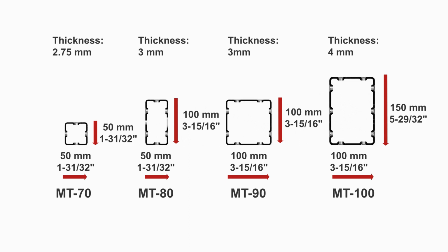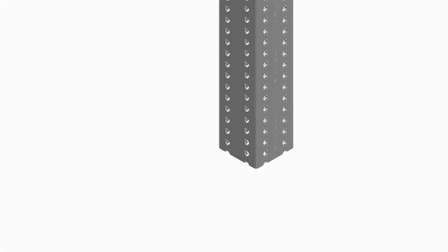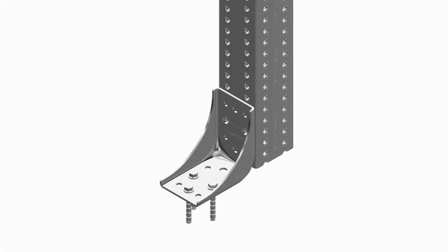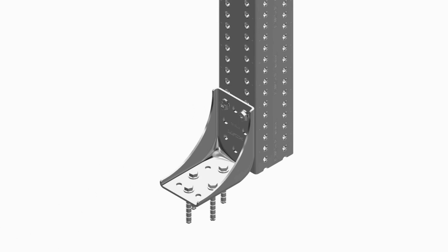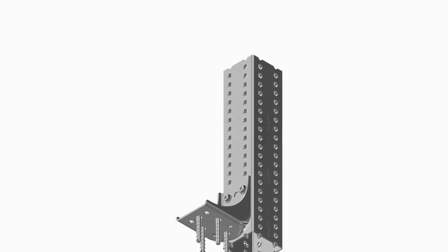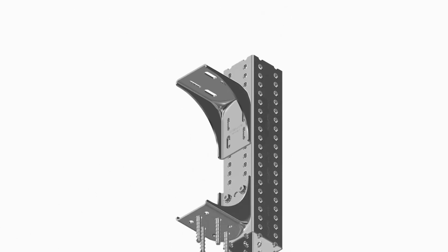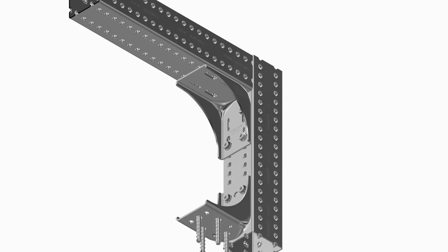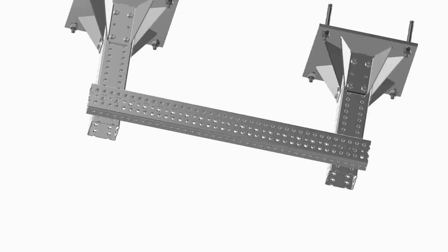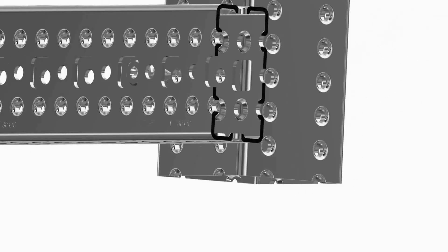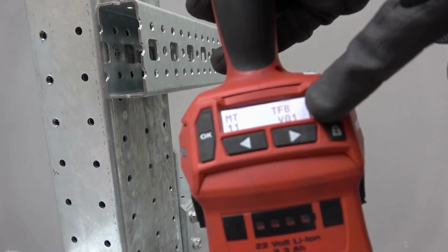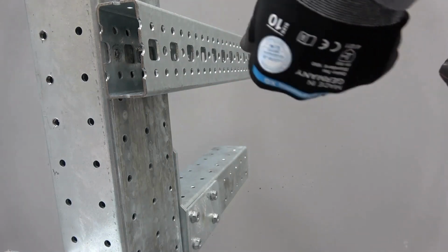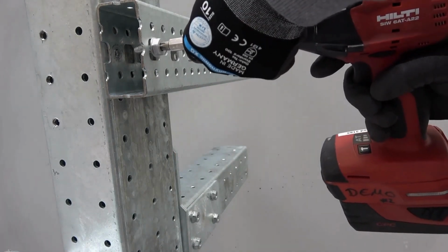These profiles were developed to deal with 3D forces, and the closed profile is the most efficient. The closed profiles are dedicated to heavy 3D structures, connecting the profiles using connectors with or without adjustability mechanisms fixed by thread-forming bolts on the surface of the profiles. Or allowing connections girder to girder without any connectors by through bolting the profiles with thread-forming bolts using active torque control module.